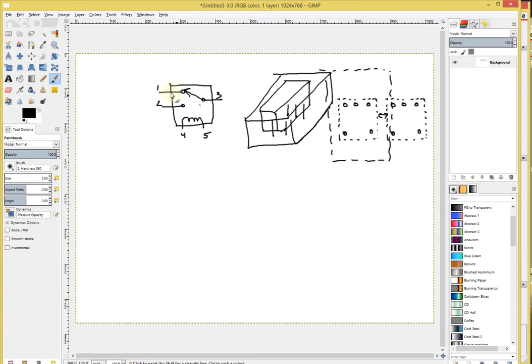So for example, here I have pins 1, 2, 3, 4, 5. Well, maybe this could be one possible pin assignment for your component. So when you look at the footprint and you inspect the pin numbers, do the pin numbers match the pin numbers on the data sheet? Maybe a different arrangement might be counterclockwise, 1, 2, 3, 4, 5. Yes, both of these footprints fit this part, but the pin assignment is completely different.